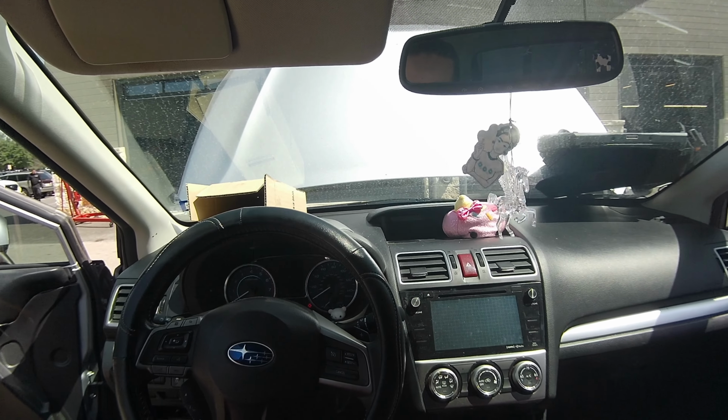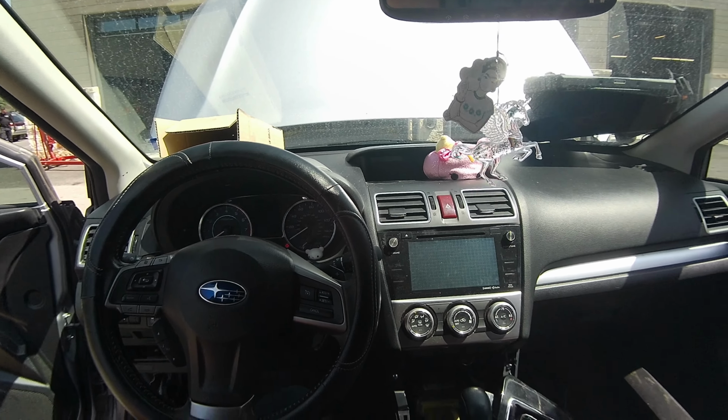I have been in those situations where people say, hey, my car won't turn on, and it's been diagnosed by two different people. Thankfully, I had the sense to calm down and check everything else in the car and make sure it's working. The windows worked, but I noticed the spot lamps didn't. That's an easy circuit, and I found an open fuse in the spot lamp, and when I replaced the spot lamp fuse, the car turned on. It's weird, and you have to watch out for that.